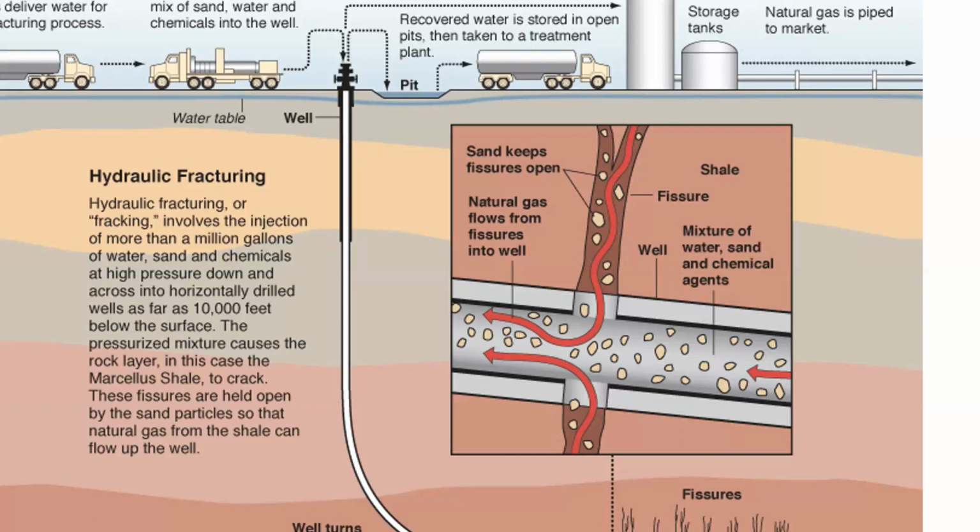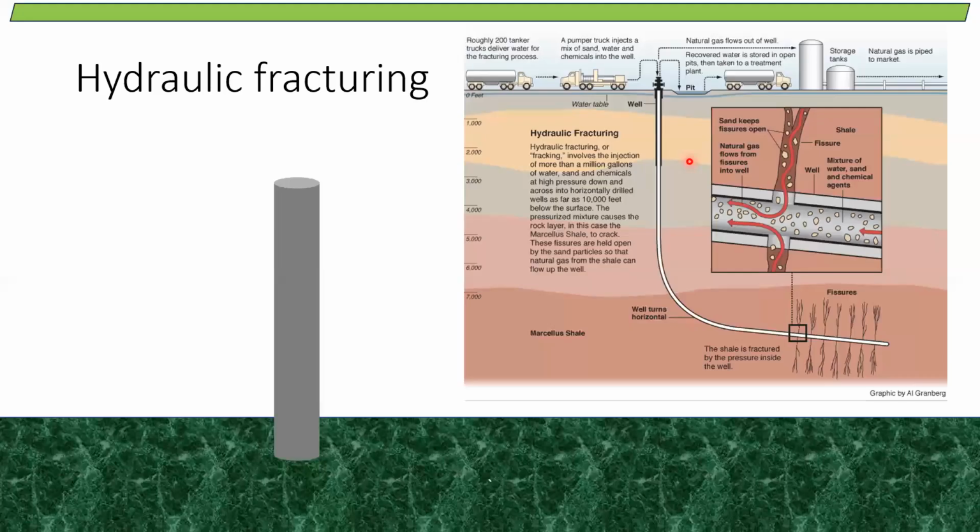I will just show you a small animation of how this will happen. First of all, this is the wellbore, and perforations have been generated over here. So it will create a channel, so that you can start injecting your hydraulic fracturing fluids. The fluids will start to enter with sand particles into the reservoir.